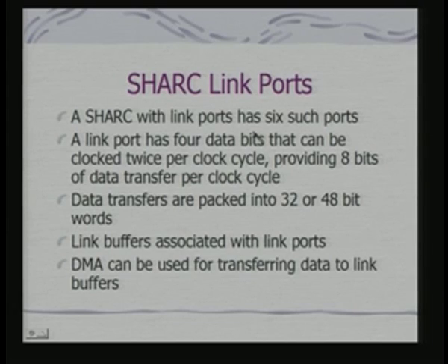Typically, such a facility is provided on one DSP processor that we had studied earlier, that is SHARC. SHARC has link ports. It's not that all SHARC processors will have link ports. Particular variants do have them, and they can have even 6 such ports. A link port has 4 data bits that can be clocked twice per cycle, so effectively it provides 8 bits of data transfer per clock cycle.